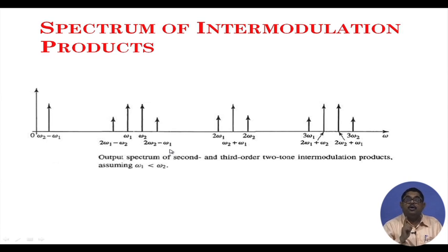So, third order intermodulation, where did it come from? Because of non-linearity it came. If the system was linear, these were not generated. Now, non-linearity also generated harmonics, but by filtering I can always remove them. These I cannot remove. So, they will disturb me, and that is where I will have to be more careful.